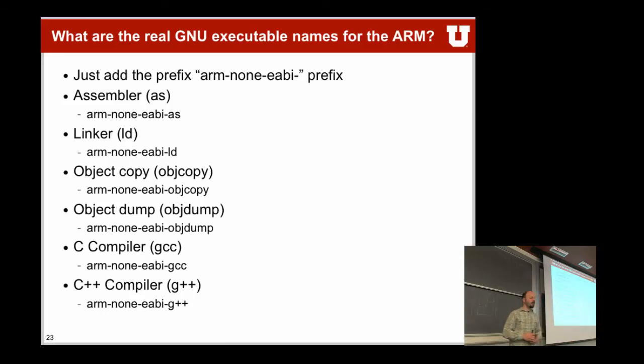There are a lot of different tools that you might already be familiar with from the GNU toolchain. The big difference is now, because we're using a cross-compiler toolchain, you're adding arm-none-eabi as a prefix to them. So if you have used GCC before, you now just use arm-none-eabi-gcc. If you used ld, the linker before, you just now use arm-none-eabi-ld, etc., etc. The key here is that these tools are cross-compiling.